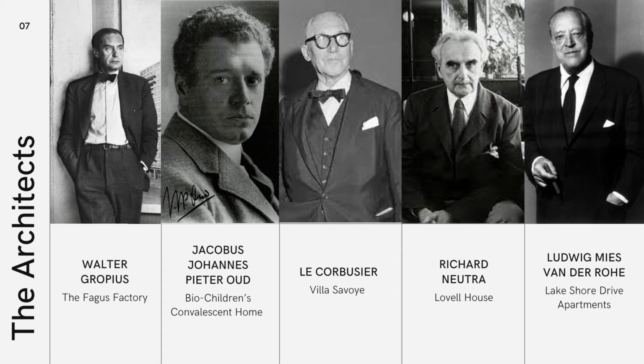First was the use of pilotis, which were thin stanchions often made of steel or concrete, used as structural support for the building. These pilotis not only lifted the structure off the floor to allow a more open ground level, but also supported so much of the building that the entire floor plan and facade could be more free-flowing and open, which are the second and third points.